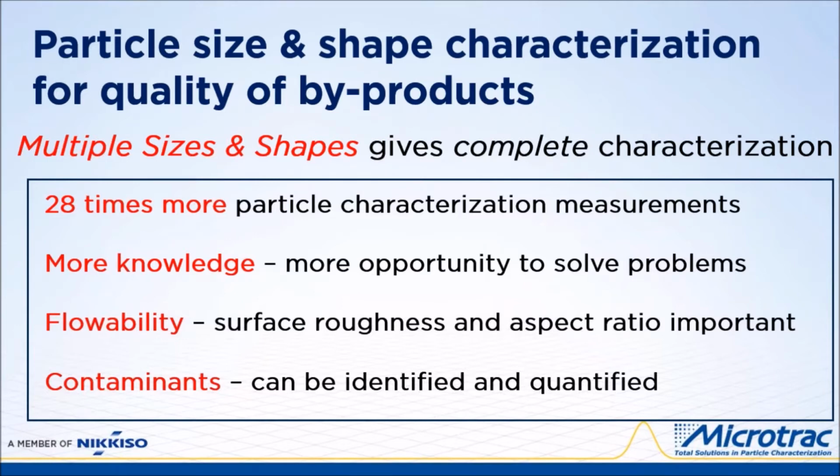As an example, particle flowability is a very general property of all particulate systems, which affects material flow, packaging, compaction, and separability throughout all process steps. Two shape factors, in addition to size distribution, have a significant effect on flowability: surface roughness and aspect ratio. As each increases, flowability decreases. This has an effect on both the preparation process and the process to convert the particles into a final product.